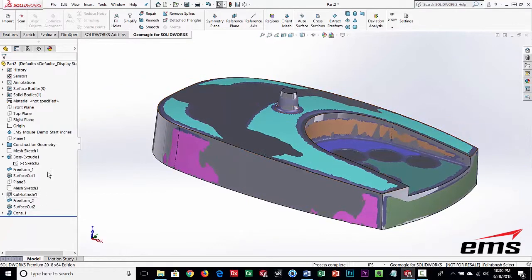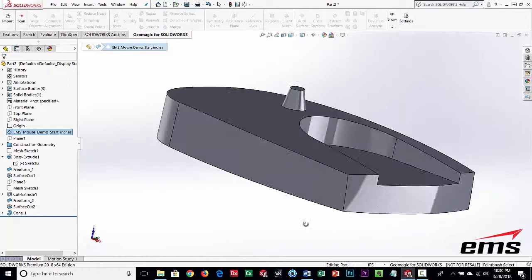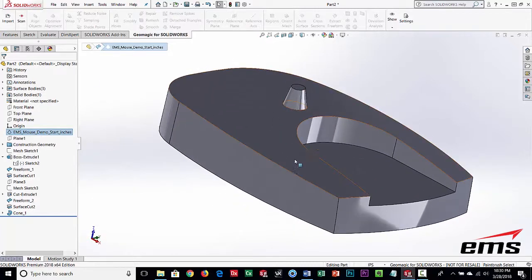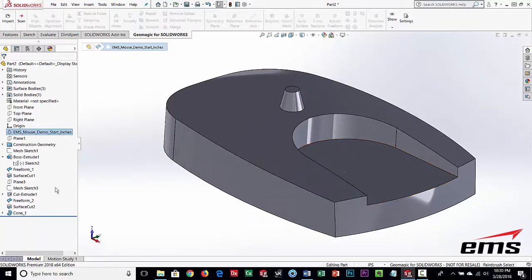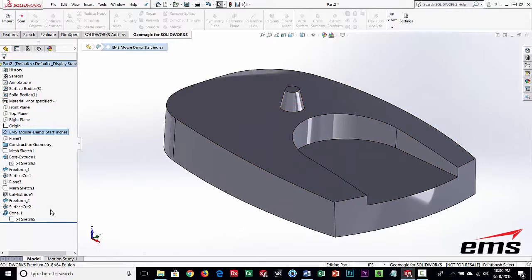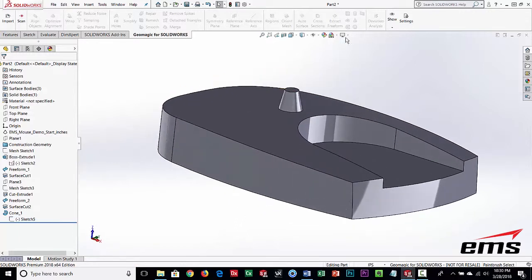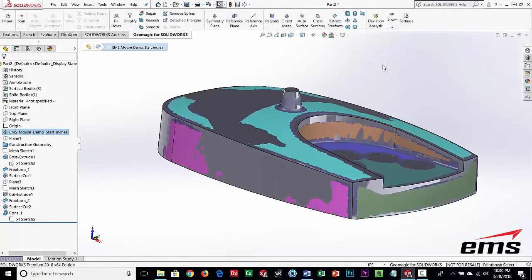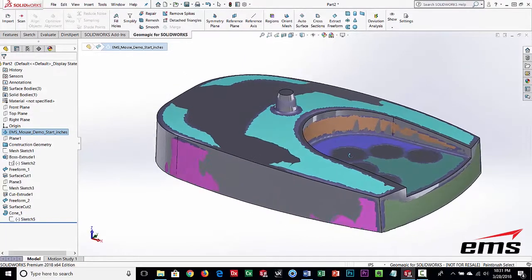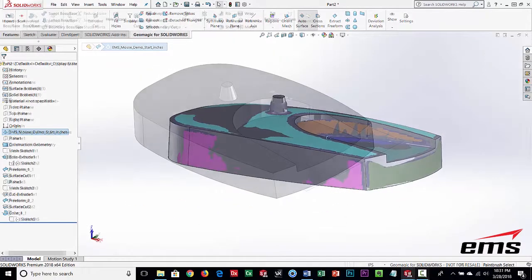And then I'll fillet and radius that off. If I hide that, you can see how I've quickly done that. And then I'll add my fillet. So I don't have to go in, and again, it builds a sketch underneath. There's the sketch right there, but it basically does that for you. So it extracts a sketch. There are a lot of primitive shapes that you can build quite quickly. So if you've got a lot of prismatic geometry, it's a nice tool.